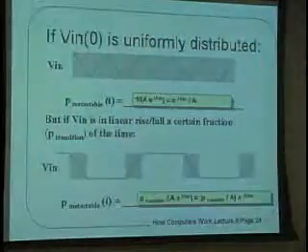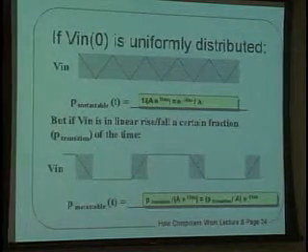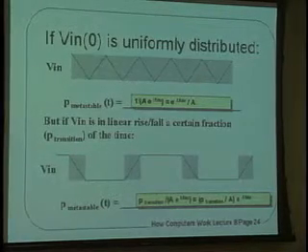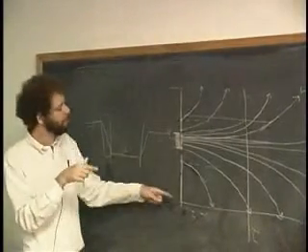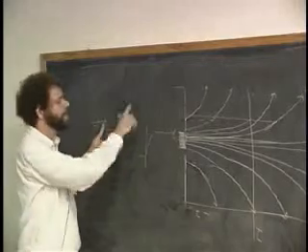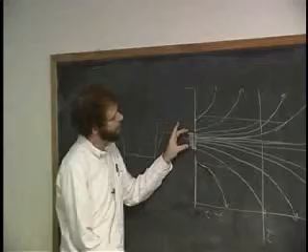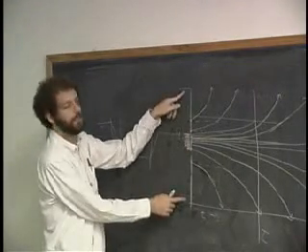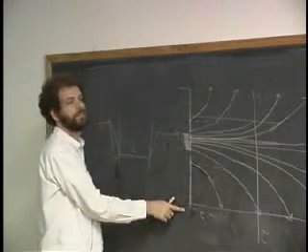And from that, I can get the question that you asked, which is, what is the probability that I will be metastable past a certain time? Well, if the voltage was going up and down and up and down, the nerd was sitting there pushing the Coke button over and over and over again, so that this voltage was always in transition, then the probability that it's going to take more than this time is this length divided by that length, because it's equally likely to be in any of the places here on the y-axis.